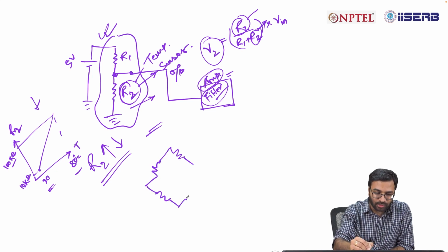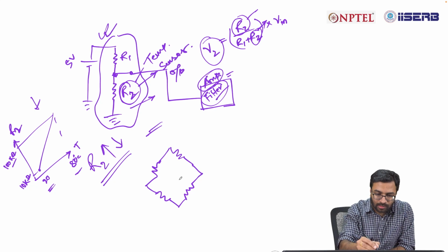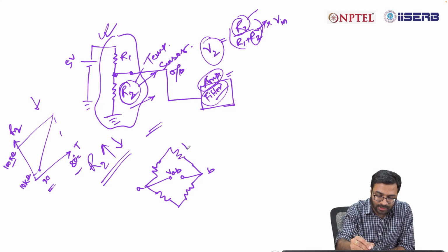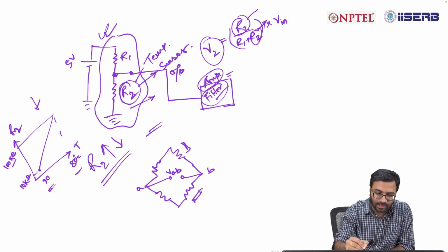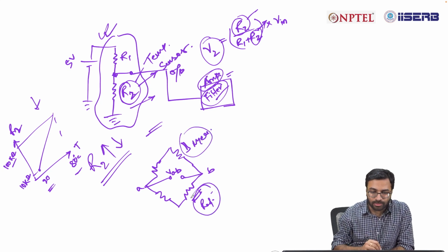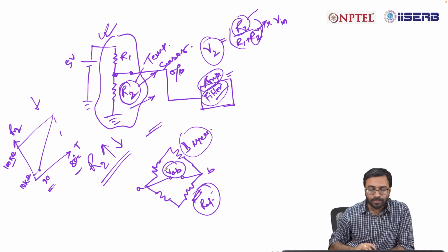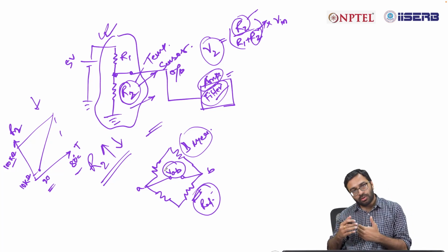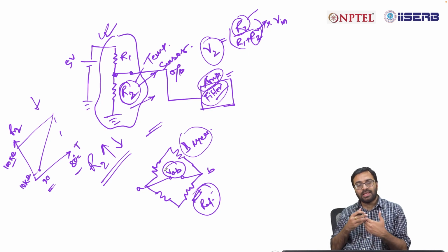If it's a Wheatstone Bridge structure, if you measure say VAB, if it is A and B, and if you have say sensors connected here, one is for reference, another is the measuring, then if there is any mismatch between reference and measuring, you will get a VAB voltage. So you can also monitor if there is any other influence present.